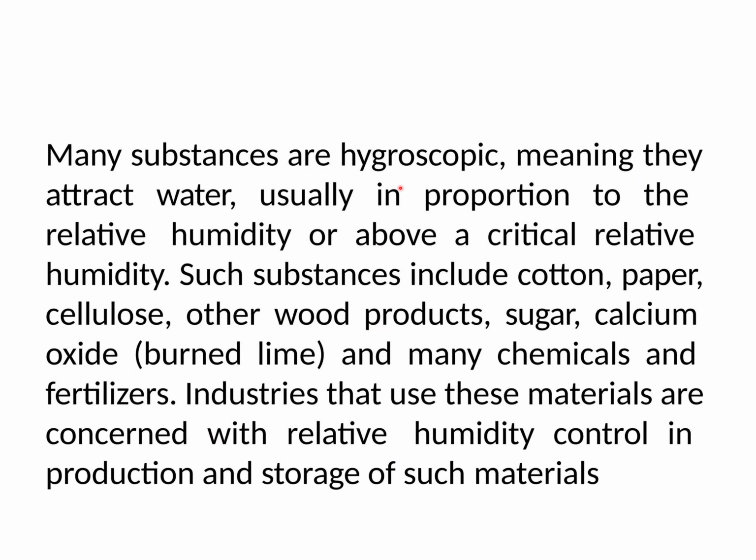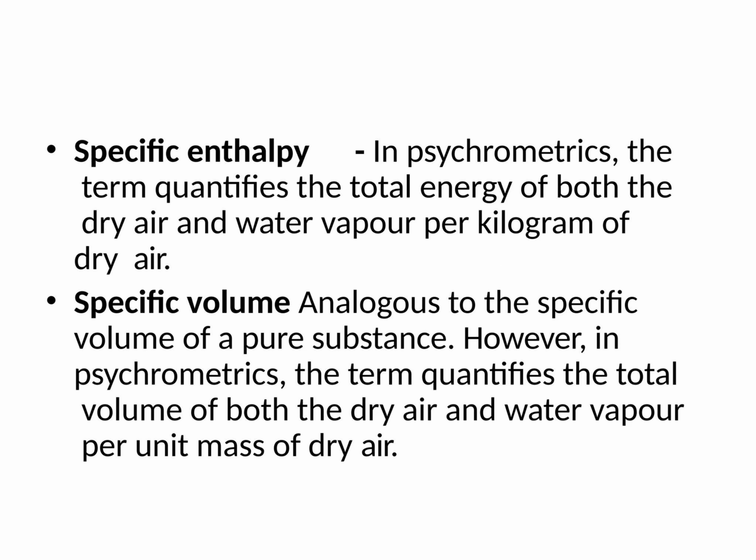So many substances are hygroscopic, meaning they attract water usually in proportion to the relative humidity or above a critical relative humidity. Such substances include cotton, paper, cellulose, other wood products, sugar, calcium oxides, and many chemicals and fertilizers. Industries that use those materials are concerned with relative humidity control and production storage of such material.